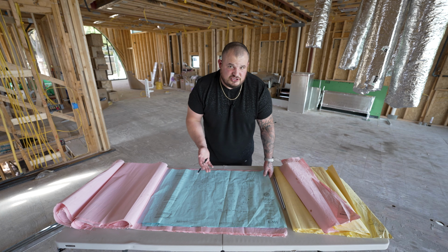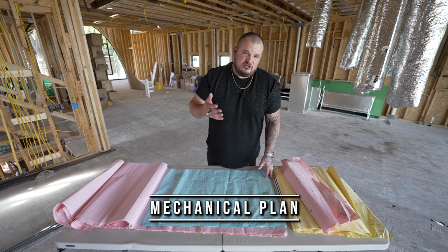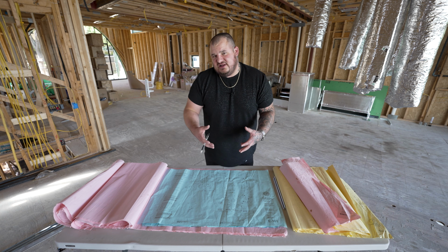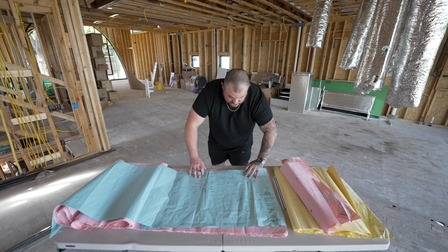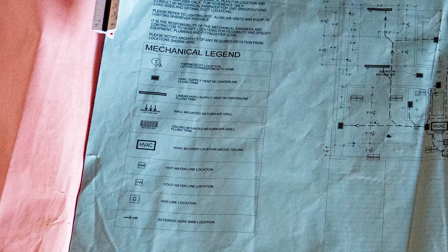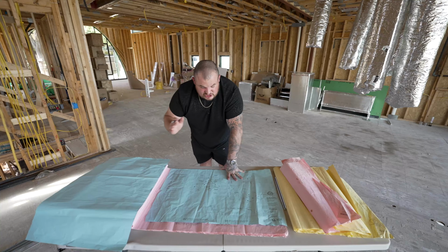Okay, now just like electric, when we're doing high-end homes, we will have a mechanical plan. Actually, in the city of Austin, every plan is supposed to have what's called a Manual J, which calculates exactly how much airflow you need, what units you need, where the returns and supplies are, etc. But now, if you look at our mechanical plan, it shows you exactly where the unit is located. Remember, there's another legend, and these legends are your friend. It has gas locations, we have hose bibs, we have all of these linear grills for our special HVAC supply ducts, so on and so forth.